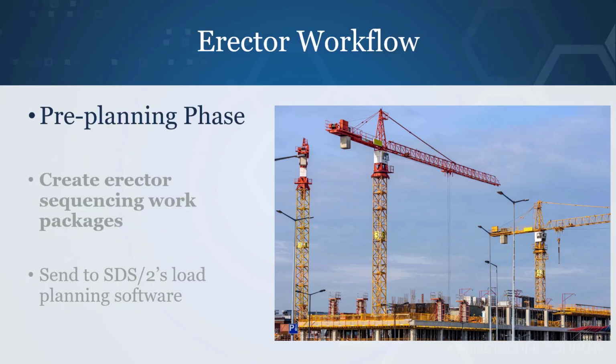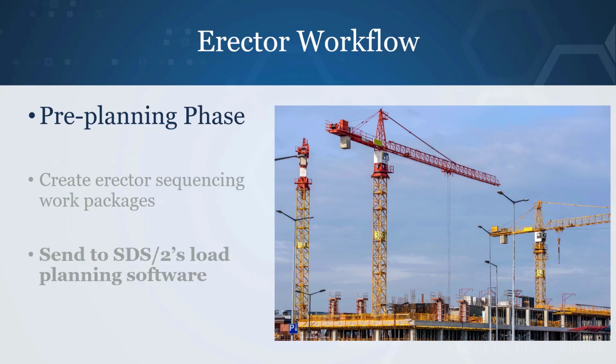So the pre-planning stage. Once I've been awarded the job, then I can start planning out my erection sequences and utilize more of the crane tools. I can put crane placements on my erection drawings. Then I can send out an IFC file of the model to Fortosi, which will be SDS2's load planning solution, and make sure that it meets the truck loader's requirements before the steel's been fabricated. I can then load it onto the truck that I want and make sure that it meets the requirements such as height and weight.